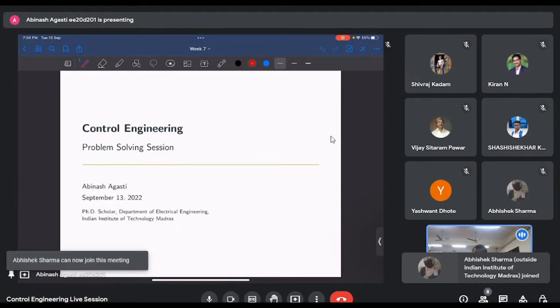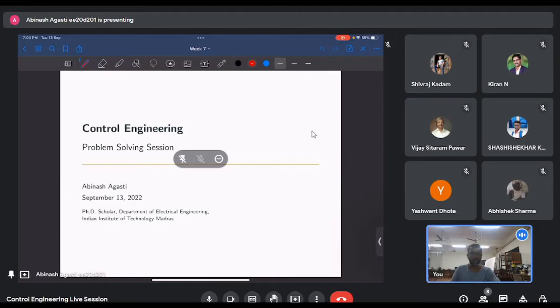Almost all sorts of feedback applications, wherever we want to do some feedback control, the first and foremost thing that people will try is the PID controller, because of many reasons. First, it is very easy to implement. You just have to tune three parameters. Easy to implement also means there is less computational burden on the processor that is doing the control.